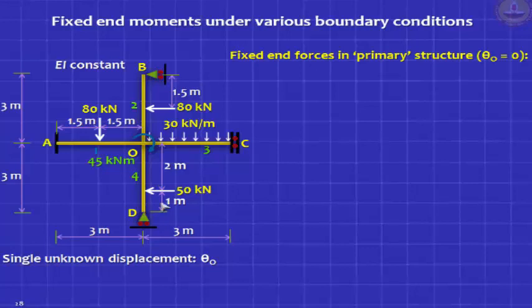Remember we did the problem with an overhang? Similarly, you must treat this. This is already known. This OD is statically determinate. I know the bending moment diagram in OD in advance. So, really speaking, I have only one unknown. You see, the displacement method is so powerful here.